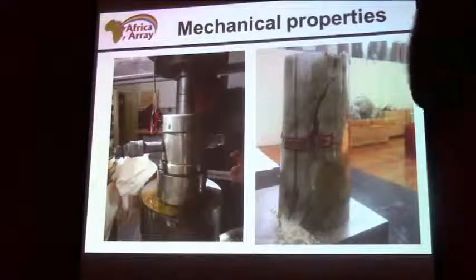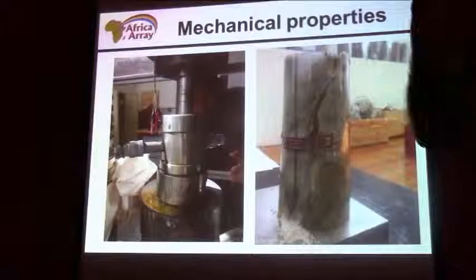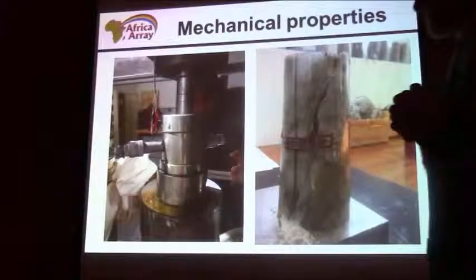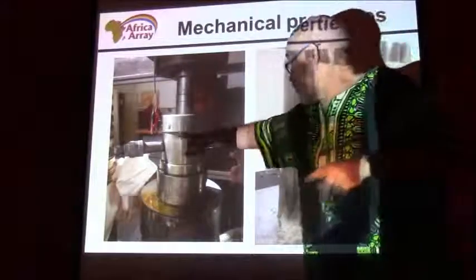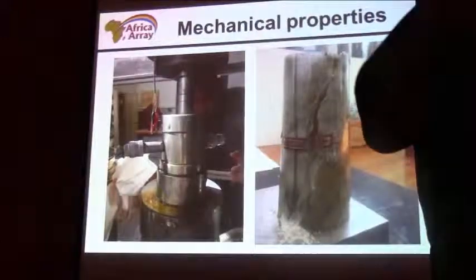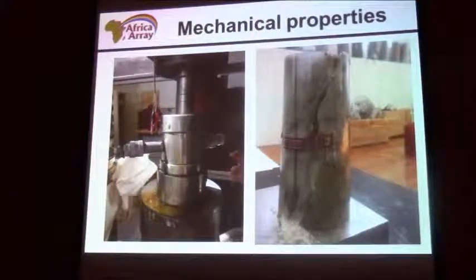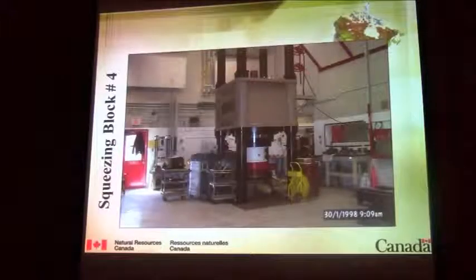But inside the earth, your rock is embedded in a rock mass, and so it's confined, and that makes it a whole lot stronger. And so we also have what we call these pressure cells over here, where we keep fluids under high pressure so we can simulate better the underground situations and find out how strong it is when it's under confinement. So we do this to do specialized testing.